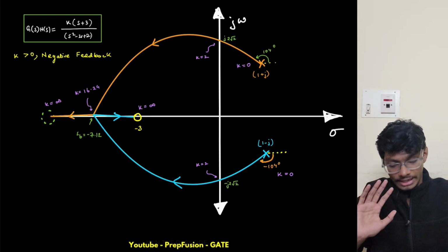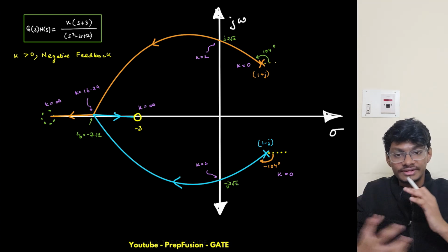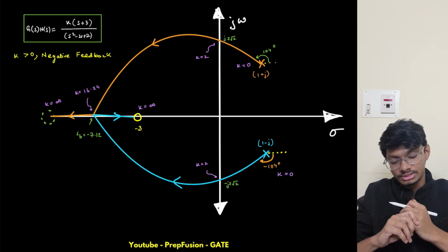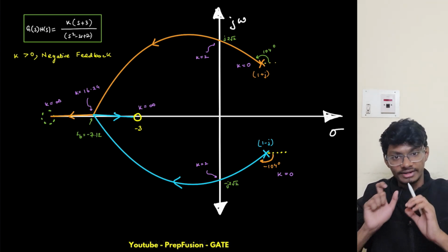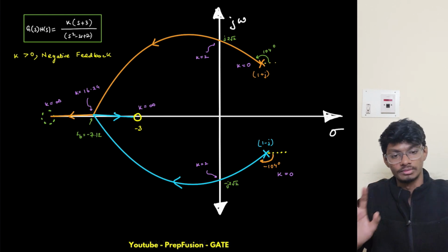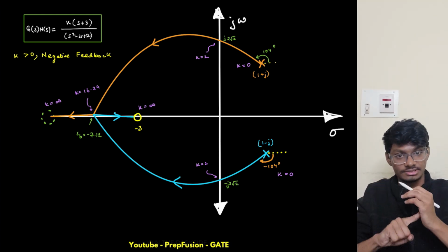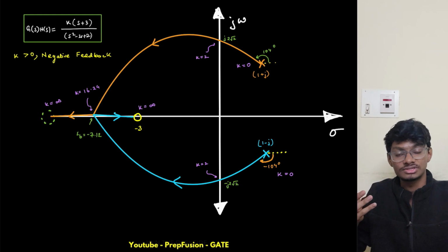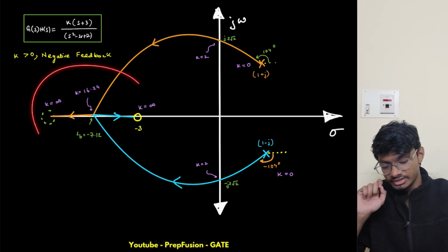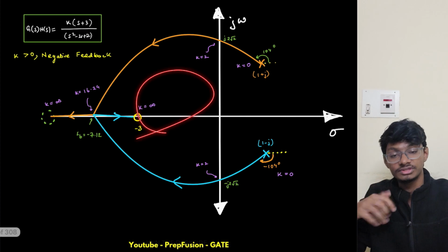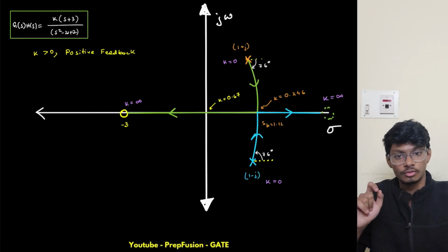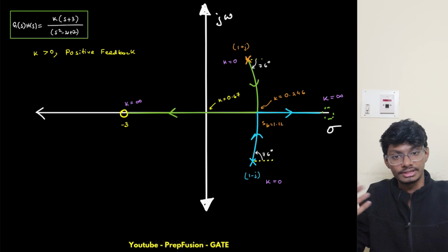So I hope you got the basic understanding of the differences between the root locus and the complementary root locus, and the link between them. It is nothing different, a similar thing, just we choose different things because the angle condition has changed. That is the only difference. Angle condition of what? The OLTF for my test point to lie on the root locus. Root locus is the locus of my closed loop poles. This is also closed loop poles with the variation of my k.